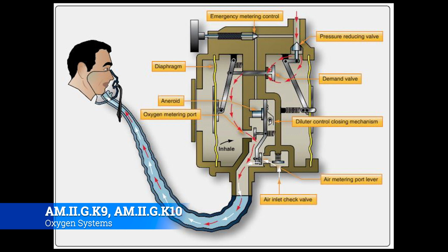If you listen to, say, Air Force videos, these guys flying around dogfighting at say 20, 30,000 feet, you'll hear their individual breaths, and that's because they're using a demand flow oxygen system to try to conserve that oxygen as long as possible. As they breathe in, it opens the valve and comes into their mouth, and when they stop breathing, it stops flowing.